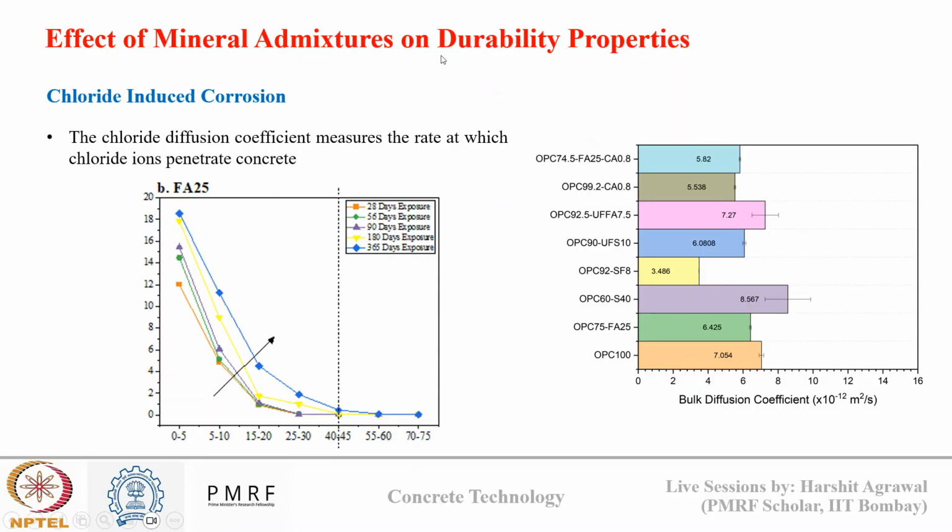So when my reinforced concrete is subjected to some adverse environment, what happens? The durability of concrete is hampered, and that's why durability properties have been taken into consideration to check the quality of concrete. By durability I mean the ability of a concrete to resist weathering action. Now this durability issue of reinforced concrete is mainly due to the corrosion of embedded reinforcement. And how does this happen? The aggressive ions which are responsible for corrosion are chloride ions and CO2.